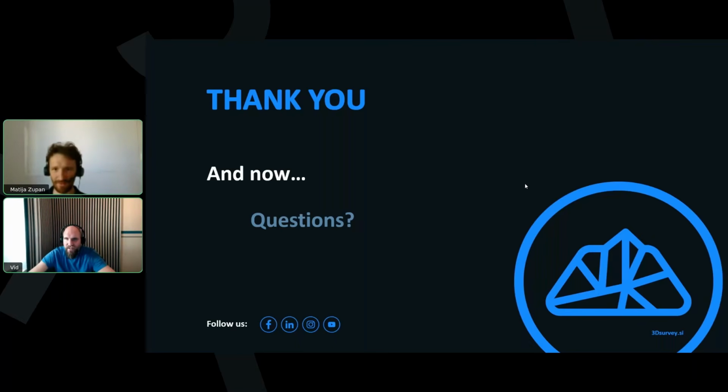The first question says, are you calculating the point cloud in a GPU data center, or do you have your own graphics cards? How long did it take to calculate the point cloud of this prison? So in this case, we did two calculations. The first calculation was the photogrammetric part. The photogrammetric part was all done on a regular desktop PC. We had about 200 images, and I think the whole calculation took about 2 hours of processing. So here we also took fewer photos to get to the final result faster.